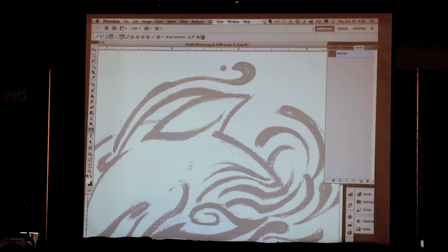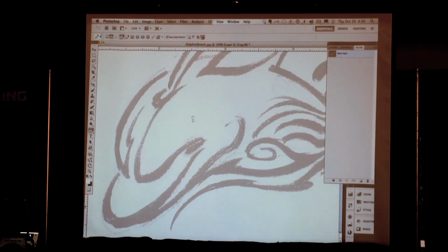So I guess with that, I'll just do one more little piece here. I'm going to find my starting point. Here happens to be a tip. I'll click and drag it out. Once again, click again, drag out the handle. Now I'm going to change directions. So in order to change directions easily, I hold my Option key, click on that point, that Bezier handle goes away, and then I can start over. Clicking out this way, and just keep going around it.